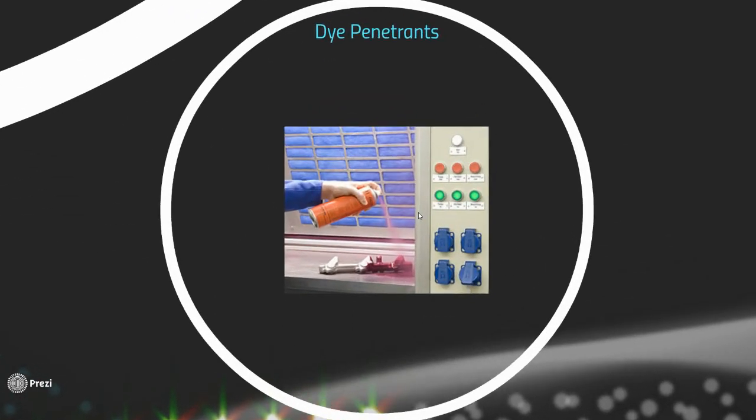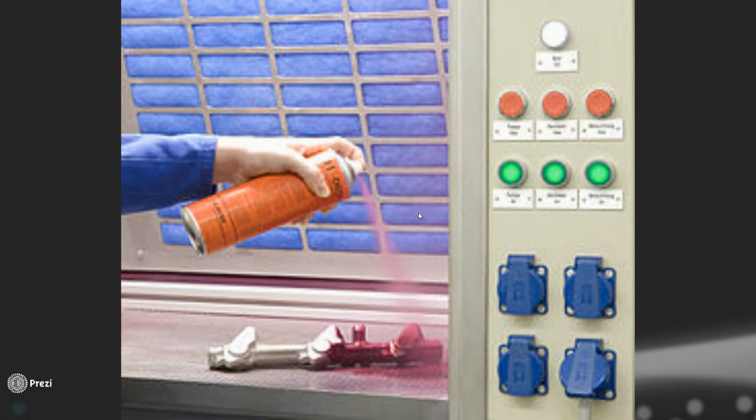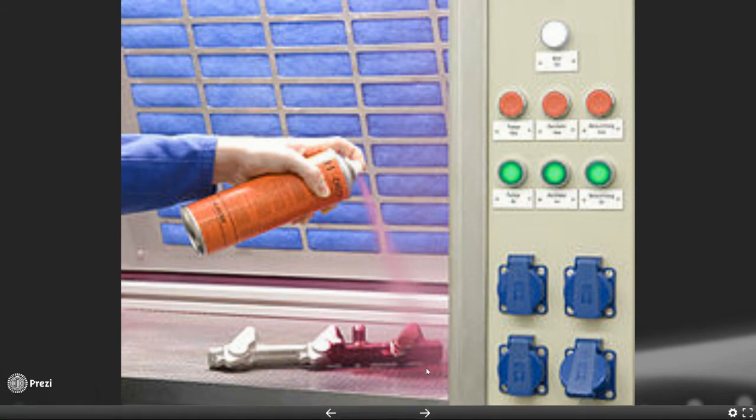Then you have dye penetrant, which I mentioned to you before, is very similar, but it's not as expensive, and it's also not as precise. What you do in this case is you clean your part, and then you essentially spray dye on it and let it sit there for a while. If there's a crack or a defect, then the dye will go into the crack or defect. Then you wipe off that layer of dye and spray on what's called a developer, which is used to pull the ink out of the crack that it went in. So when you see blotches of ink in places, you know that there is a crack that ink got pulled out of.